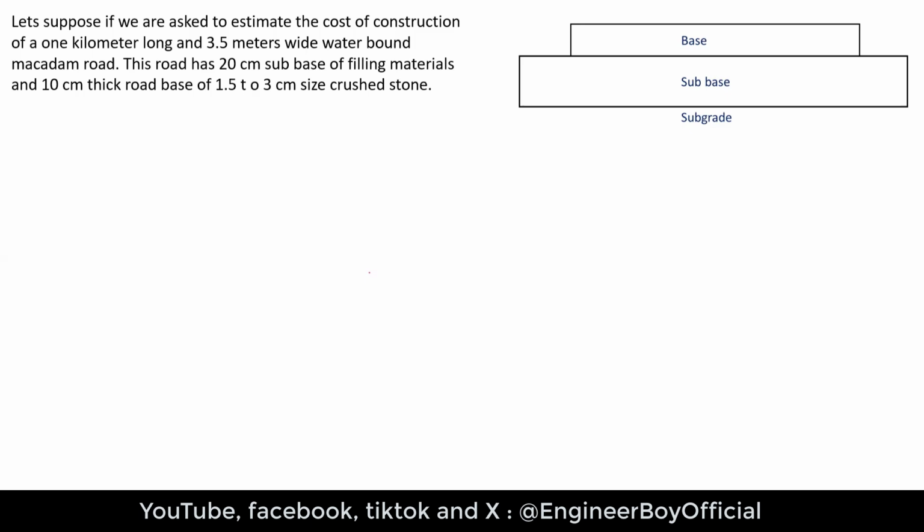All right, so we have the base, which is 3.5 meters. This is just the breadth, or maybe the width, of the base layer. The base layer is 10 centimeters thick. And we have, of course, the sub base, which is 20 centimeters thick. Those extensions are 50 centimeters, or maybe you can say 6 inches, on both sides of the base layer. So we can get the width of the sub base. That's very simple. All right, let's move ahead to the solution.